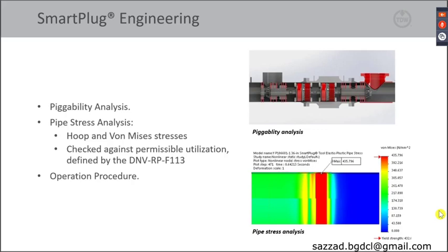Another of the critical concerns is the potential of excessive pipeline hoop stress. This is hoop stress approaching the elastic limit of the pipeline at the location of the slips and the packer of the plug modules, from these stress finite element analysis plots shown in the figure here. Excessive hoop stress can occur during either the initial setting or during the isolation period. However, spreading the stresses over both the isolation tool plug modules, each of which has been assessed individually against full potential pipeline pressure, helps ensure that the hoop stress does not approach the elastic limit of the pipe and further enhances safety during the operation.